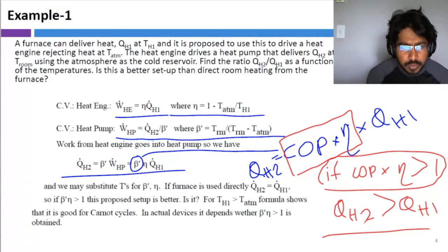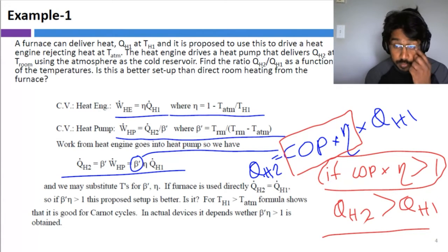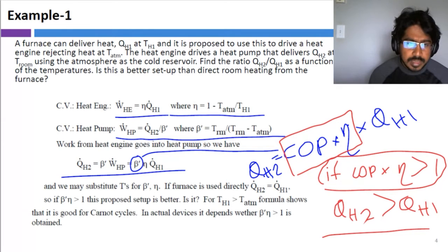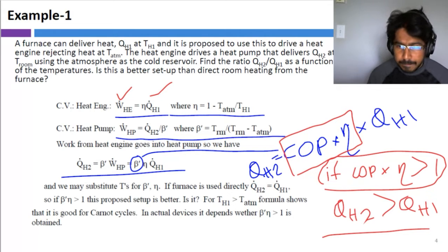W dot and QH dot. If it is given in the rate form, you can use the rate form or the absolute energy form in an efficiency equation. The only key is if you use one component in the rate form, the other components have to be in the rate form. So that is the thing. Okay.